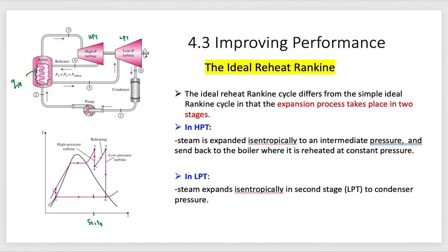So in a boiler, it will reheat the steam and the temperature of the steam will increase to T5 here. And we can see here that the temperature is increased from T4 to T5, and usually T5 is equal to T3.